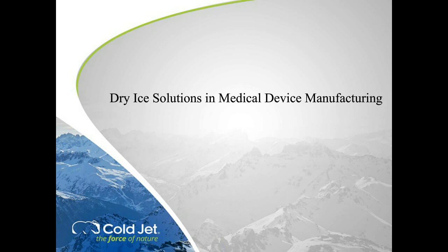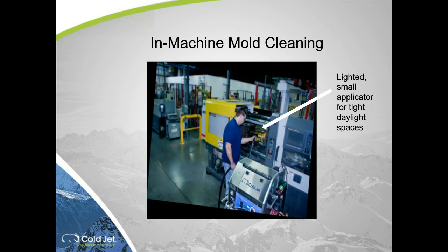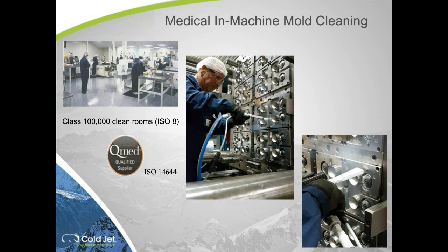What are the common applications in medical device application with this dry ice technology? In-machine mold cleaning is definitely number one. In-machine mold cleaning at operating temperature is a device that rolls up next to the press. You interrupt the process and you clean the parting lines. He's cleaning the A half of the tool now. He'll turn around and clean the B half of the tool. He is cleaning all the off gases off of the cavities themselves, off of the vents. If the leader pins and ejector pins are part of the venting system, they'll clean those as well, likely relubricate them before they go back into process.